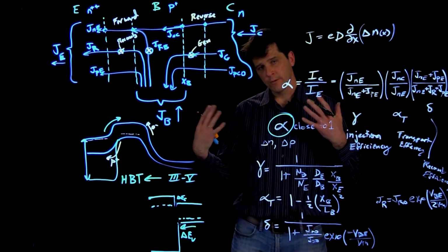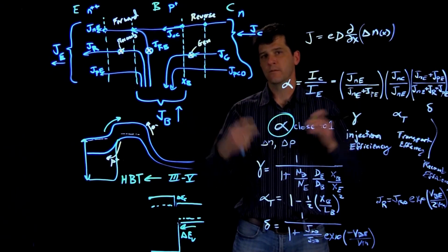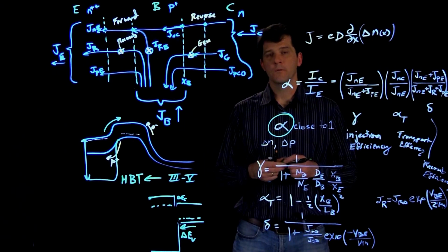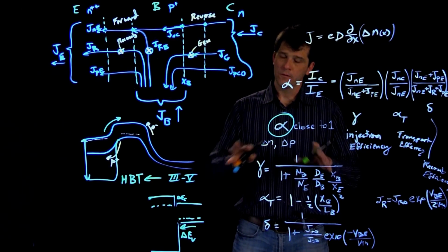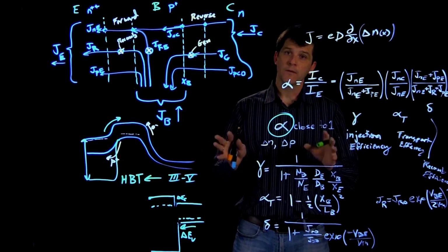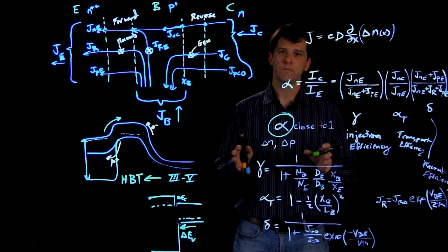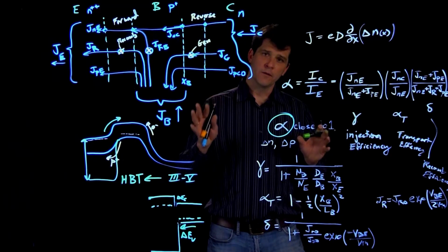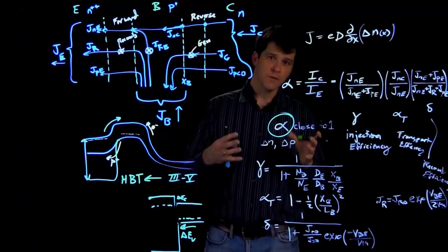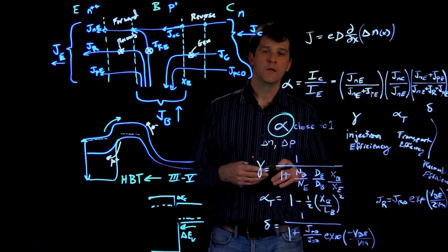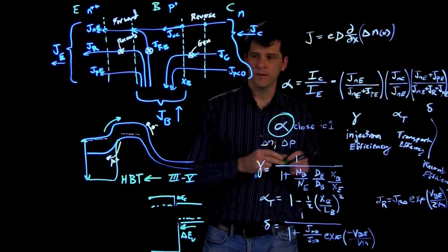Now, when we were talking about MOSFETs, we mostly concentrated on on-off behavior, although we did talk some about the nonlinearities. The bipolar junction transistor turns out to be a little easier place to talk about the concept of transistor gain. Now, I want you to think in your heads and go back and apply these ideas of gain. You get a larger current or voltage in one part of the transistor when you input a signal from another.